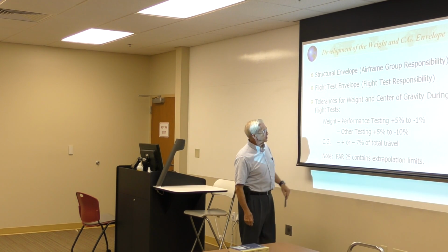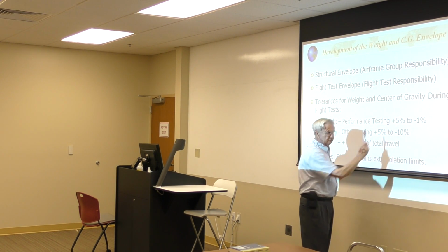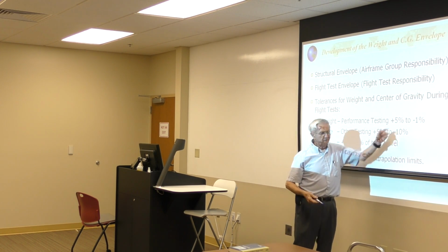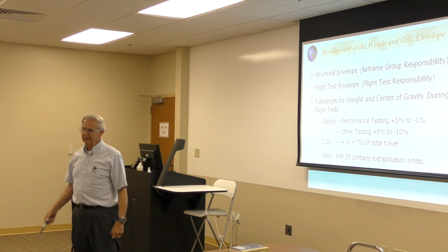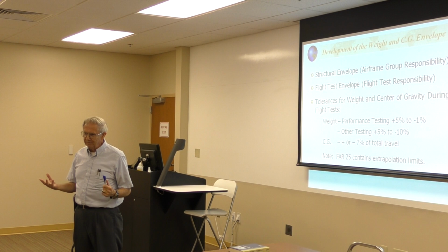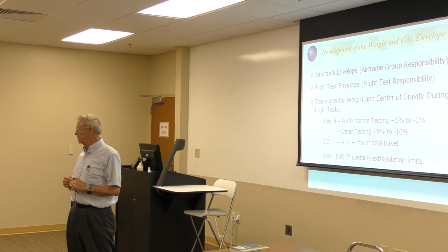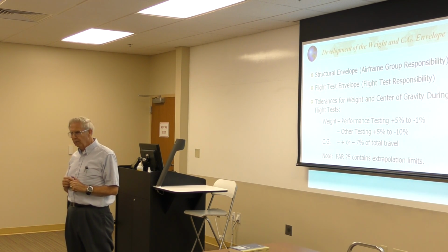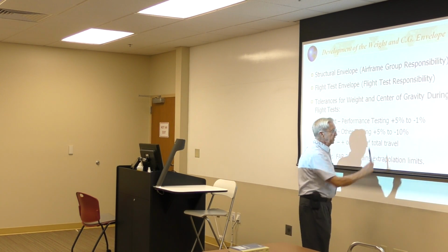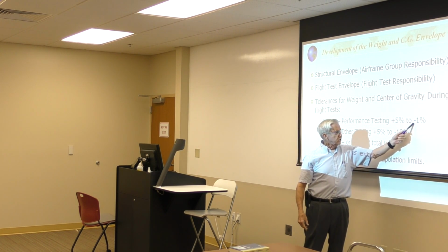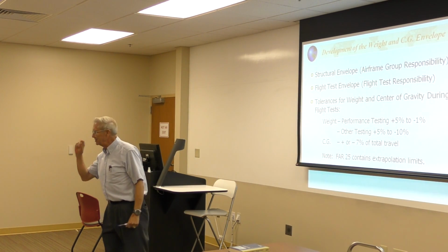Okay. Some tolerances for weight and center of gravity. For flight test purposes, they allow us, not in this course, by the way, but in a flight test, like I went out and flew last week in this Thrush Ag plane, the W sub S for that airplane is 10,500 pounds. My takeoff weight was 10,921 pounds, okay? So they allowed me to overload the airplane for the flight test. The reason is, notice that they don't allow you to underload it, so to speak. 1% isn't very much.